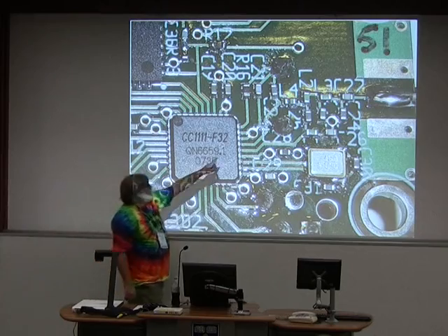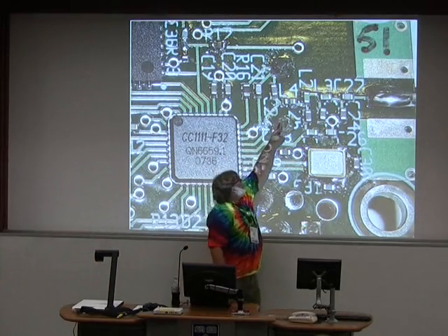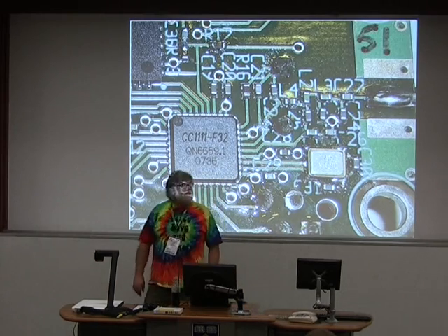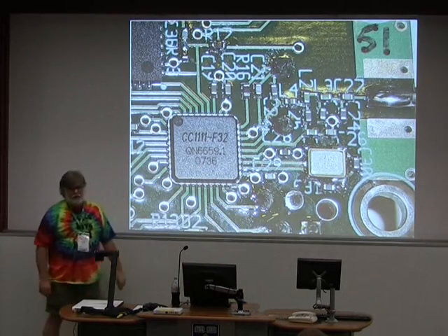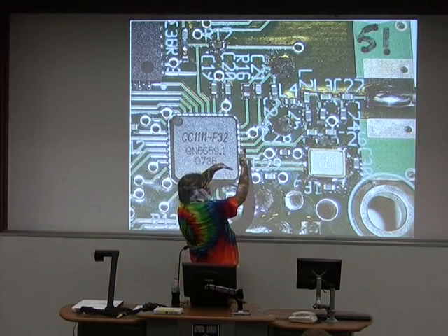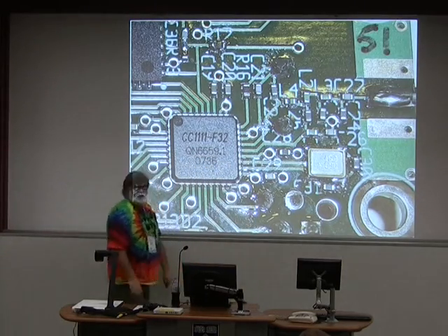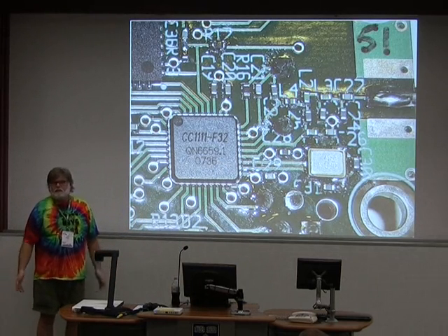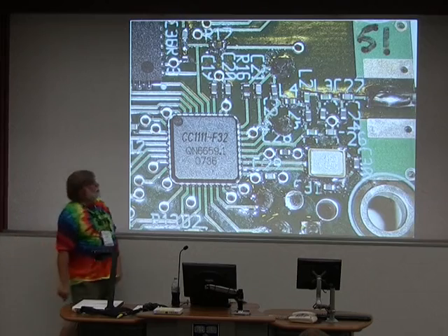And you'll notice that the little parts that have a greenish tinge, like that one and that one and that one, are inductors. And you notice the orientation of the one in between. I've got two of them like this, and the one in between's like that. It turns out that that's good for 0.3 of a dB, something like that.